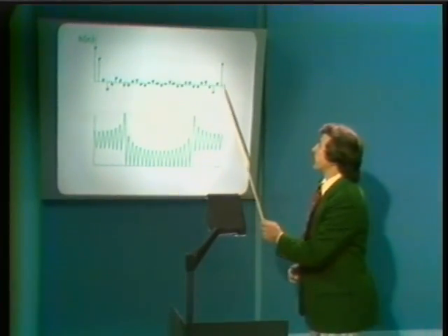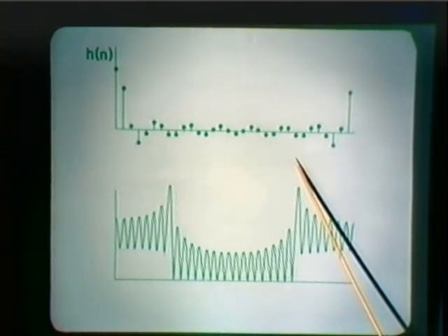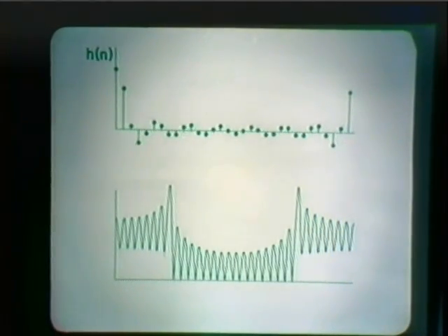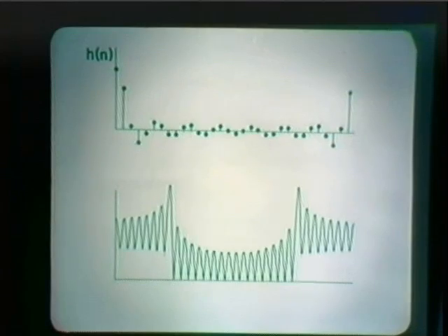This unit sample response is simply the previous one circularly shifted by approximately N over 2, or N minus 1 over 2. And in this case, the frequency response characteristic is even worse than it was in the previous example. So here we have a frequency response that has very wild, large fluctuations in the pass band and even in the stop band, but still goes through the same frequency samples that we had specified previously.